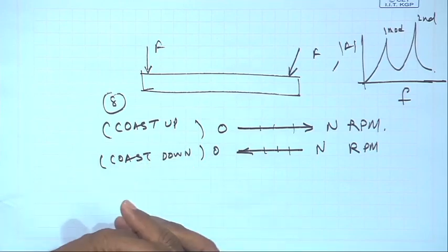So, in summary, in rotordynamics we understand the dynamics of rotating shafts, which is inherently present in any machine, and the effect of the bearing stiffness and how it plays with the critical speeds of the shaft. No shaft is, strictly speaking, rigid. They are flexible, so they will have many critical speeds.